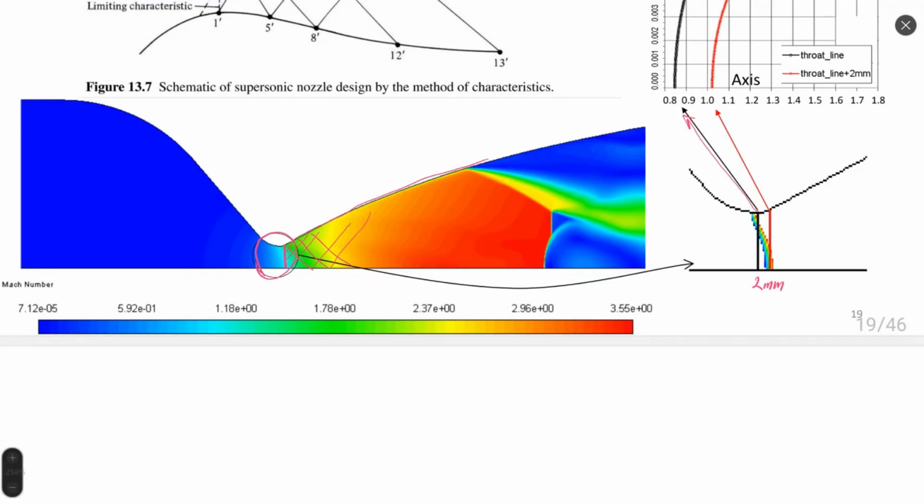You can see that, for example, here it is isentropic. We cannot see any shock waves in the part of supersonic expansion. We can see shock waves after, but this is because we have low pressure inside the nozzle, not because of nozzle shape. Right? Low pressure inside the nozzle means very high expansion ratio or very low pressure inside the combustion chamber. It is not related to shape, it is related to the relation between pressure in the nozzle and atmospheric pressure.